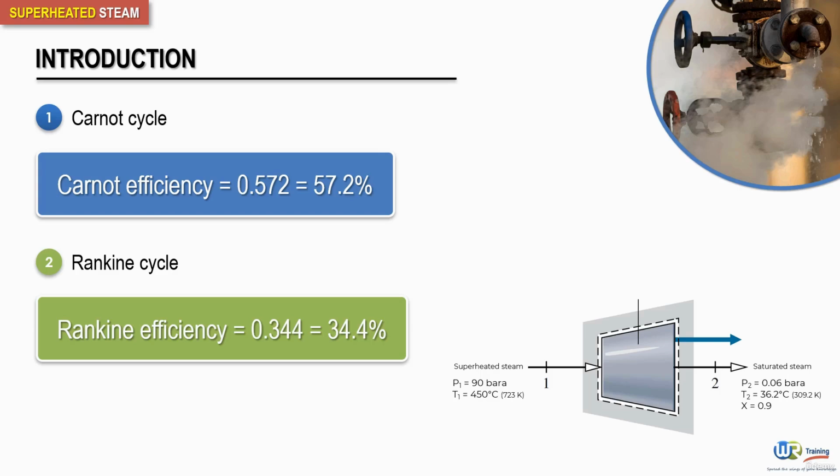Now, it is important to note here that the figures calculated in this example are for the thermodynamic efficiency and must not be confused with mechanical efficiency. Although the efficiency figures appear to be very low, they must not be viewed in isolation, but rather used to compare one type of heat engine with another. For example, gas turbines, steam engines, and diesel engines.